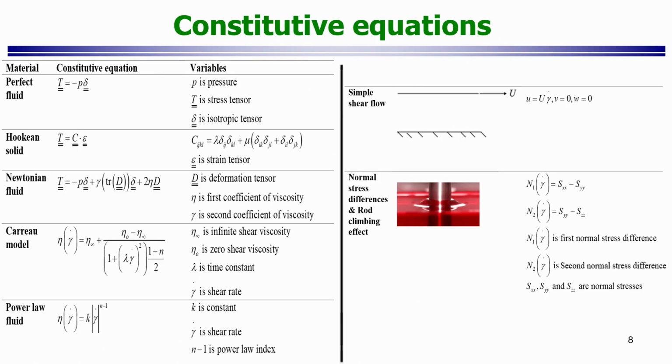After that, we moved on to distinguish an important set of equations which is called the constitutive equation. So, we first started off with understanding that they are different than the conservation laws, and then we enumerated many of the important constitutive equations that we find commonly in solid and fluid mechanics. For example, the perfect fluid, and the Hookean solid, and obviously the Newtonian fluid. And here once you use this constitutive equation, you will end up with the Navier-Stokes equation once you do the proper formulation for the conservation of linear momentum.